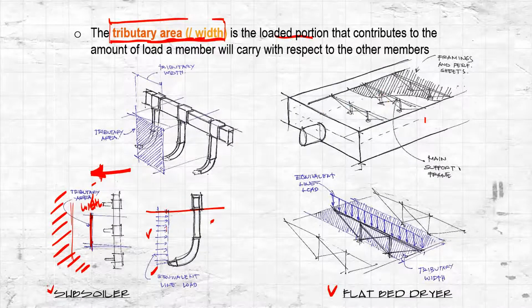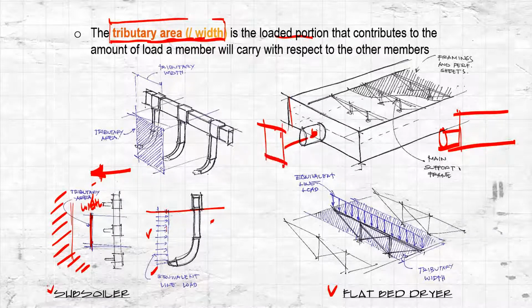One equipment for drying is the flatbed dryer, and this flatbed dryer is basically a bin. If we draw the side view, this is the supply blower or supply air. From a heat source, let's say a furnace or a diesel burner, this blower will introduce the hot air.